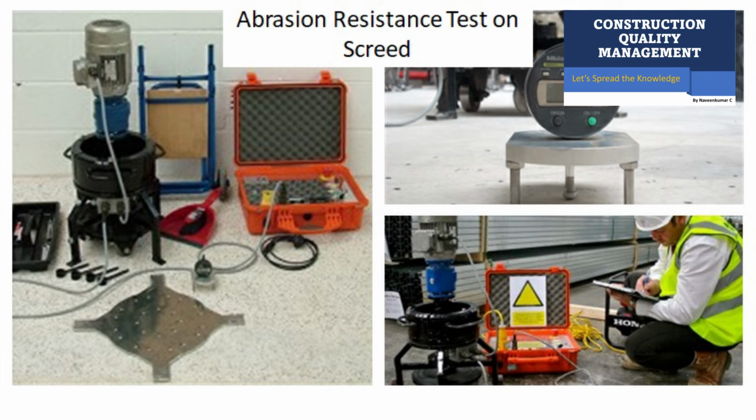Then the wear resistance is determined from the average wear depth, that is the impact created by rotation, maybe around 10 micron or so. Then the value is noted by using a digital or analog measuring dial, or dial gauge as we call it. The results have to be matched with the design intention report.